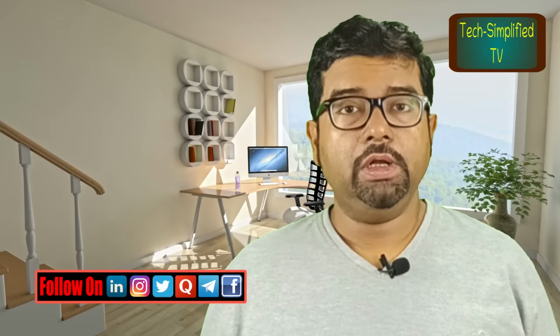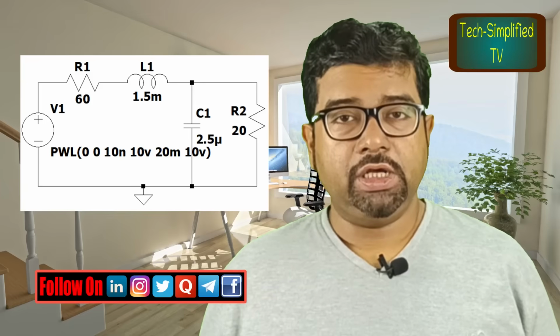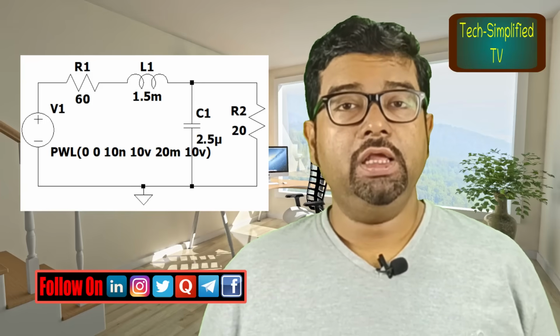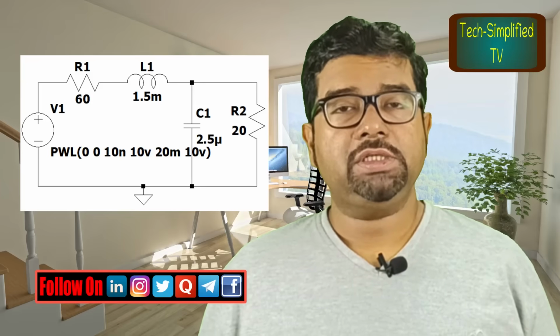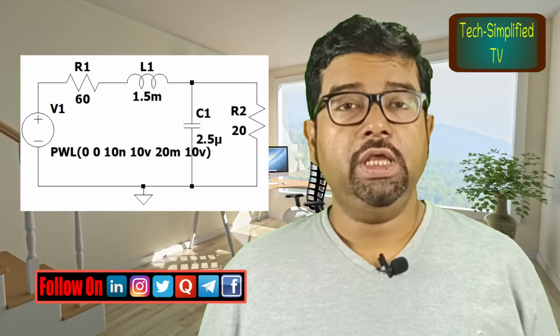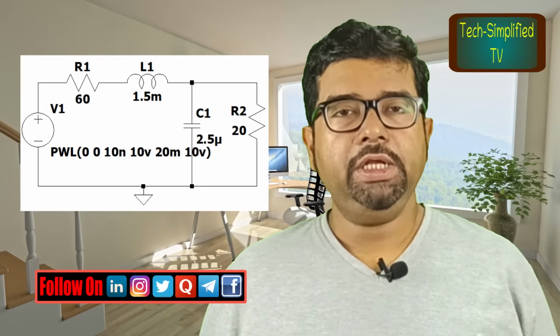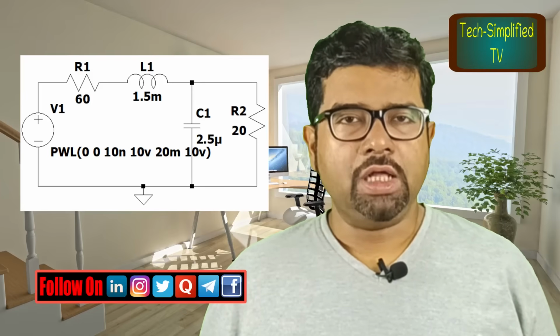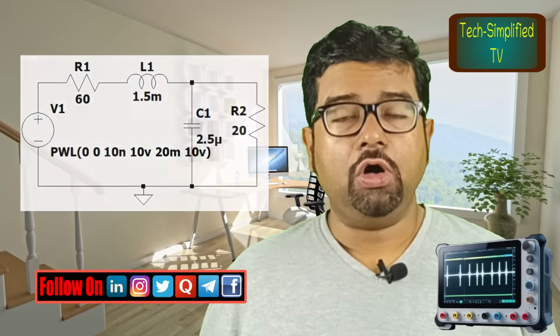In this episode, we will construct an LCR circuit where the resistor and inductor are in series with the voltage source, and one capacitor and a resistor are in parallel with the same voltage source. We will apply a PWL source and transient analysis to observe the time domain response of the circuit.